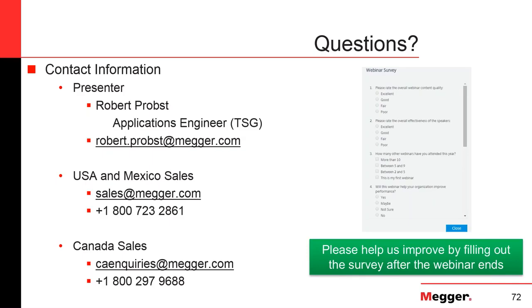Another application would be to check the entire protection scheme, not just the differential that applies to everything. You inject current through the primary of the CT, which is the bus, and then the CT will pick up. It will feed that into the relay. The relay hopefully has the right settings and will trip the circuit breaker.